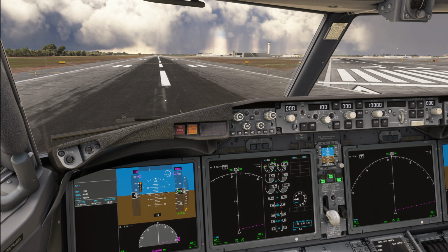Now, a couple of possible transitions here include: if you've previously been in altitude hold, it will revert to MCP speed so that you can pick some speed up again. Likewise, if you've been in VNAV ALT or VNAV PATH in a level segment, it would revert to MCP speed, and all other modes are going to remain unchanged. Now note that the flight control computer logic on the 737 MAX inhibits autopilot nose-up stabilizer commands when the trailing edge flaps are extended or when the airspeed is 3 knots or more into the amber bar.